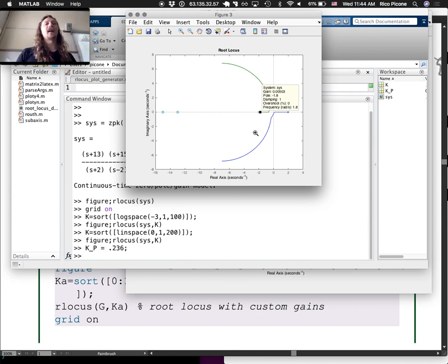So yeah, and then if you had poles, so that we had that list of things... times when the assumption holds, like having the other poles or zeros be 5 times further out, 5 times further to the left on the complex plane, that would be a good condition for that assumption. But you're probably still going to make the assumption anyways, and then you're going to test it.